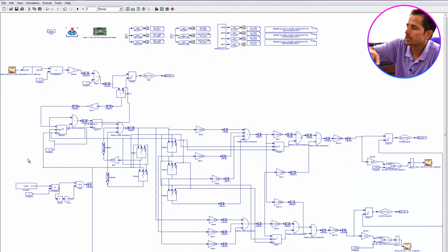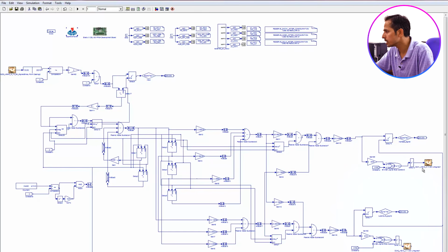The yellow one is the input signal, which is fed to the ADC, and the green one is the in phase component, which is shown on the green channel through this D2A1, and this is the quadrature phase component, which is shown over the blue channel. So this is the overall HDFT program, and I have shown that the fundamental frequency of any input signal can be extracted. The signal could have been a square wave also, and its fundamental frequency can be extracted.